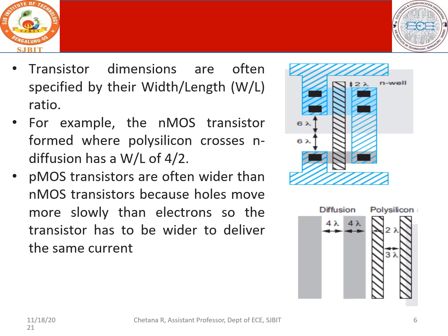the transistor being created. Normally in PMOS transistors the width is more, because in PMOS the holes are the charge carriers and they are very slow compared to the mobility of electrons. Once the width is wide enough, more holes can flow, and as a result the mobility of holes is made comparatively little better than the earlier flow.